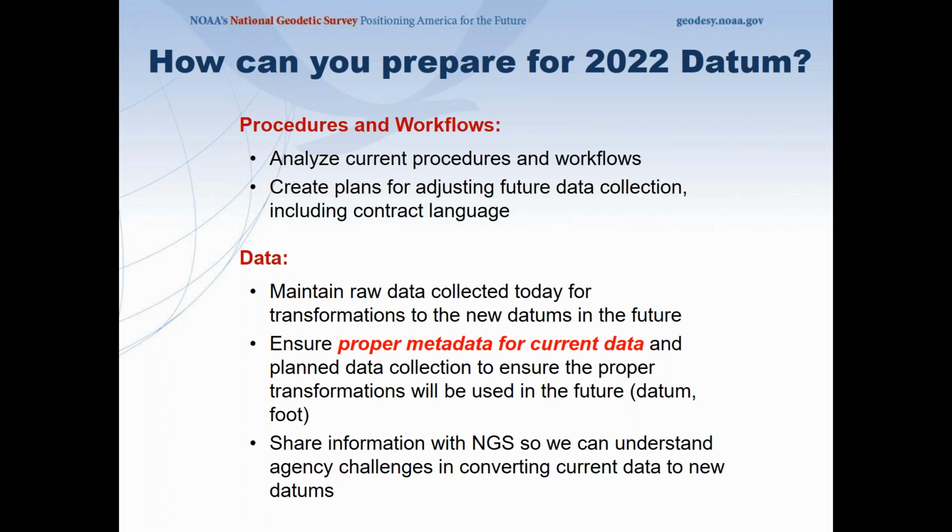And this is the biggest one: ensure proper metadata for all current data. If you know the metadata, we know what you have and what you're starting with, we can go from one to the other. But if you just say, here's the data, and you don't tell if it's state plane coordinates, UTM, if they're feet, meters, or whatever, I've gotten projects like that. The only way I can decipher things is I just have to go down a checklist and figure it out. If I know where the work is, I can try to figure things out. We have this problem in the Pacific with a lot of users.